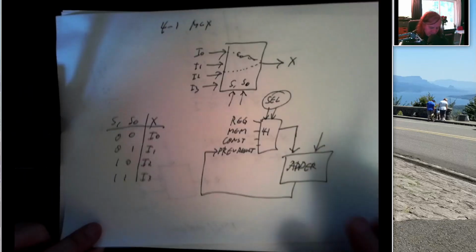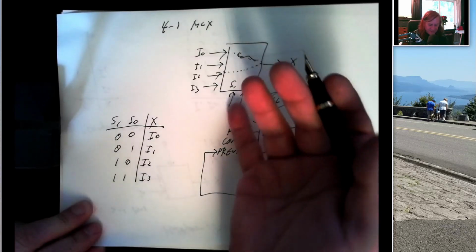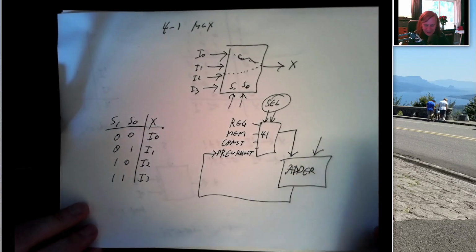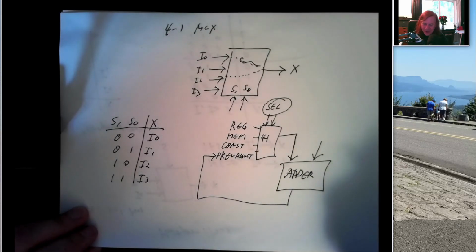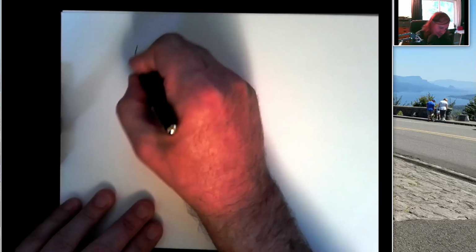Another thing multiplexers are useful for is building more multiplexers. So, if we wanted to build this 4-to-1 circuit, it's 64 possible input combinations. That's a big truth table, right? And we'll get some reduction when we do a K-map and cover adjacent ones. But there's a different way we can describe a 4-to-1 multiplexer. And it works by using a set of 2-to-1s.